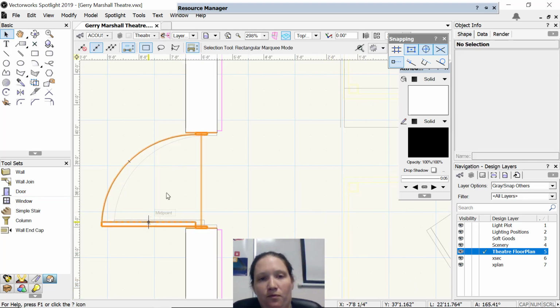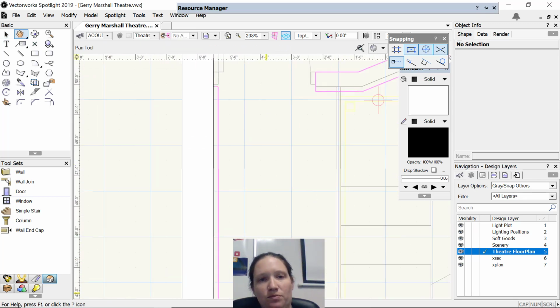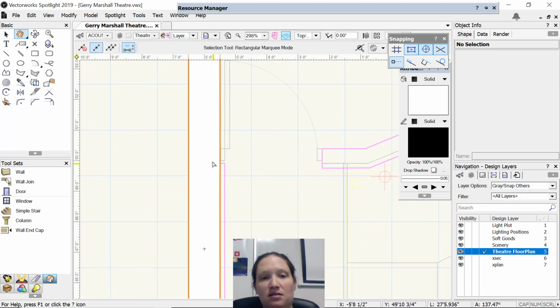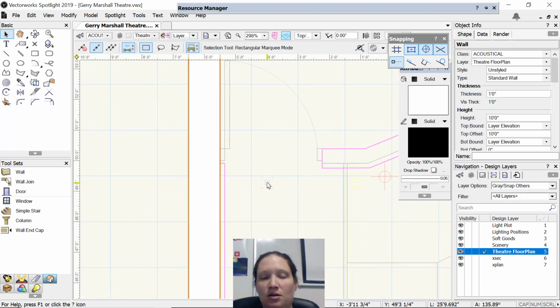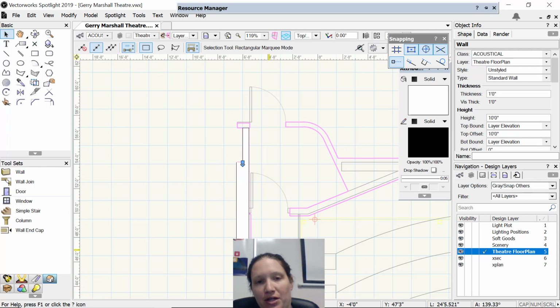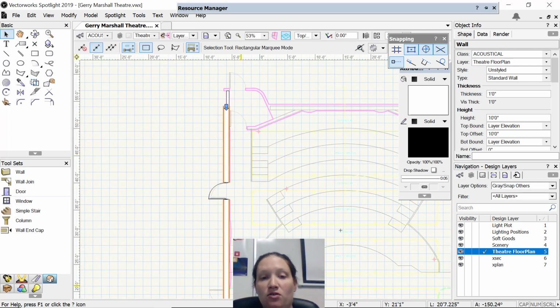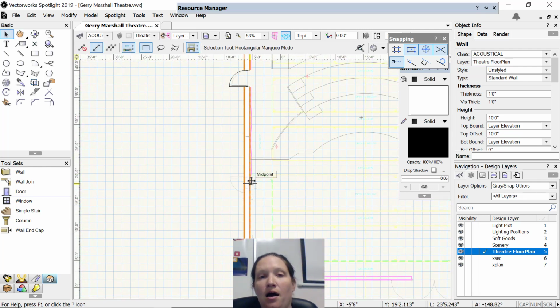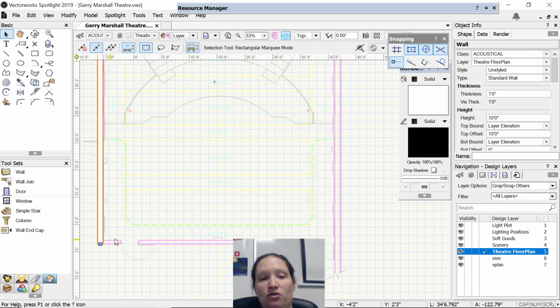Right now, it's not perfectly aligned because this wall is not matching up. So those are some details that I can figure out, because it looks like maybe the wall changes as it goes through there, right? As it goes through this door opening, it looks like this wall moves further inside. So that's something you can figure out and tweak as you go. But you'll want to add your doors in that way. You can join your walls together. Doors like this you can just place as a double door, and those are all options in the door tools.